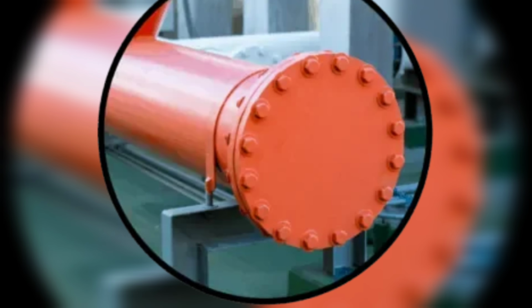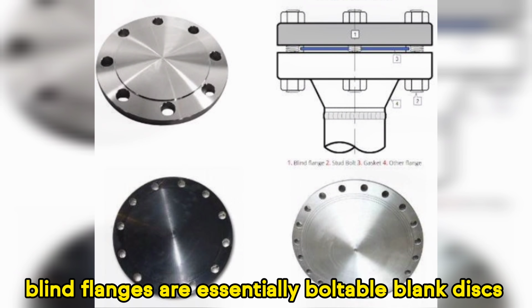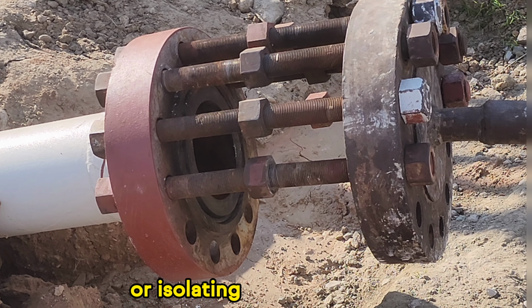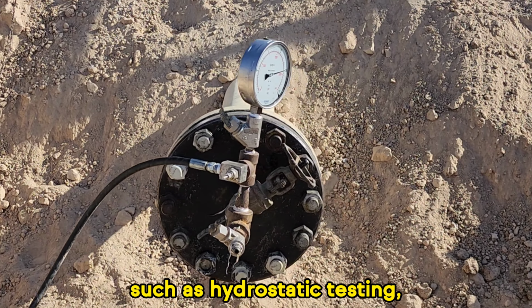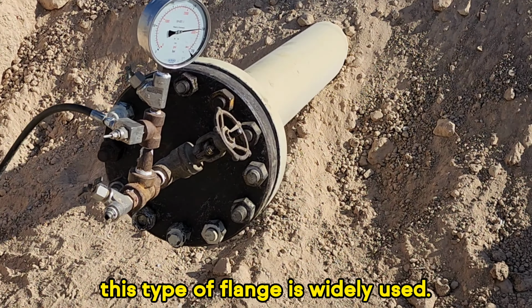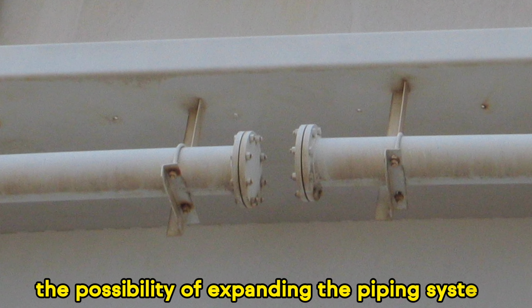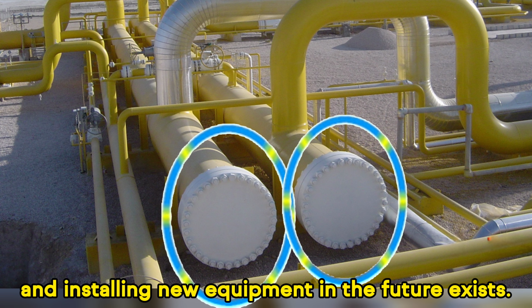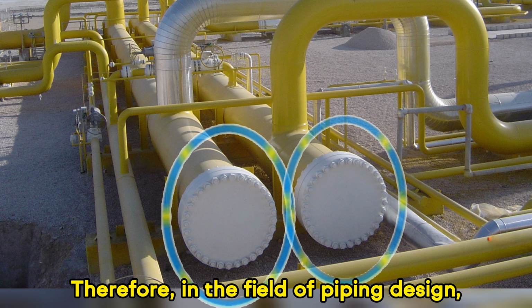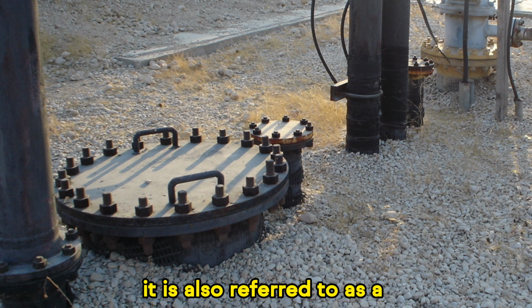Number 1. Blind flange. Blind flanges are essentially boltable blank discs that are used for terminating or isolating piping systems. In non-destructive testing such as hydrostatic testing, this type of flange is widely used. By utilizing blind flanges, the possibility of expanding the piping system and installing new equipment in the future exists. Therefore, in the field of piping design, it is also referred to as a future connection.